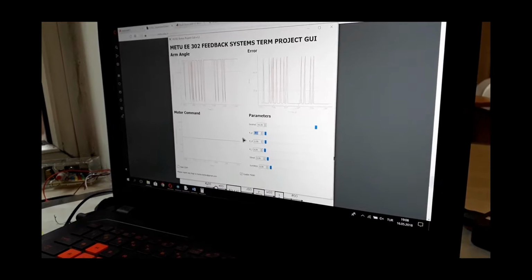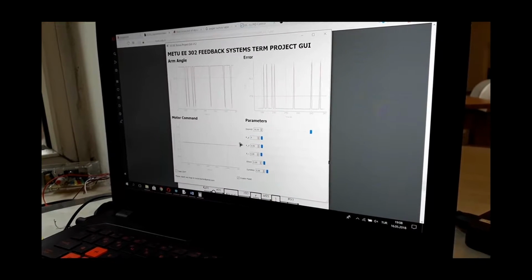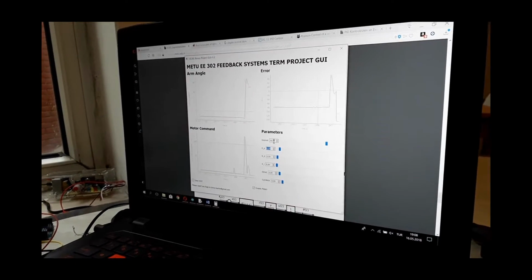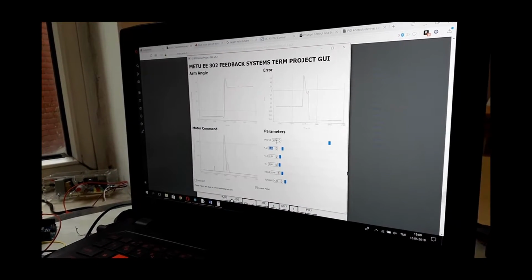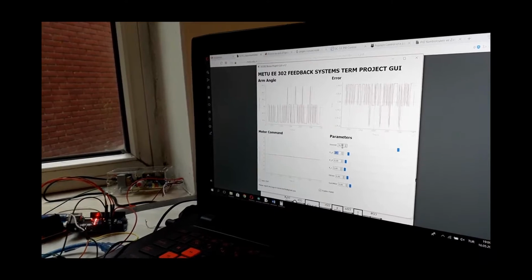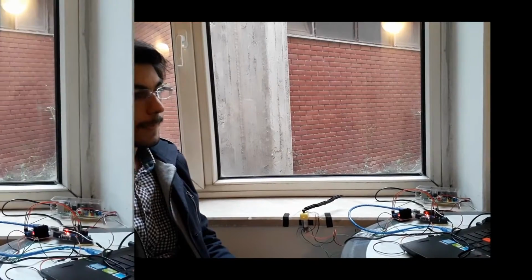We set the desired angle to 50 degrees and the Kp value to 4, and you see the motor comes to 50 degrees with an overshoot of approximately 25%. And the corresponding rise time and fall time come out approximately: the peak time is 0.23 seconds and the settling time is approximately 0.45 seconds.